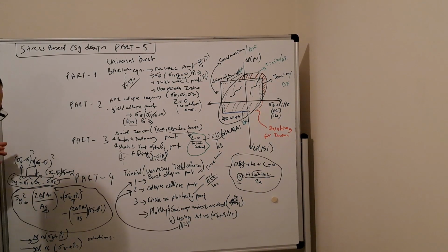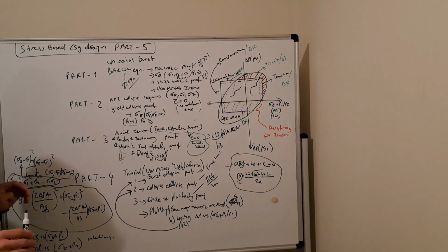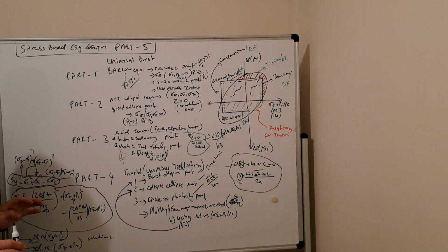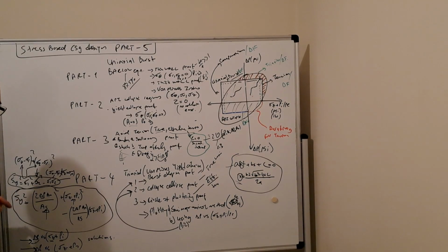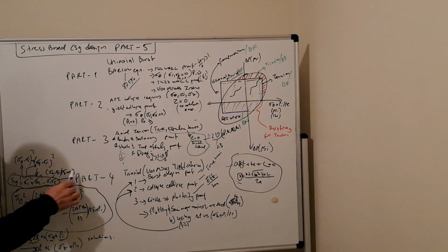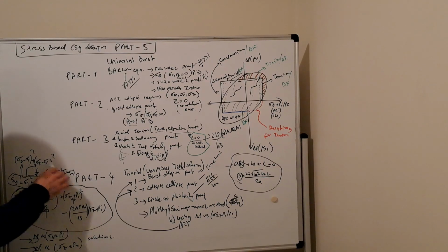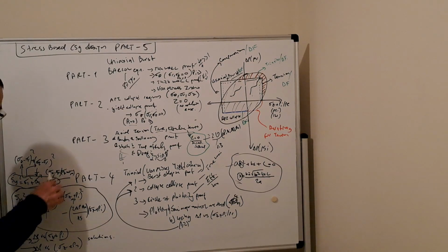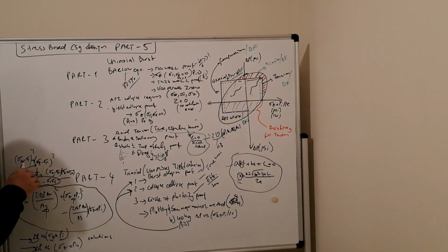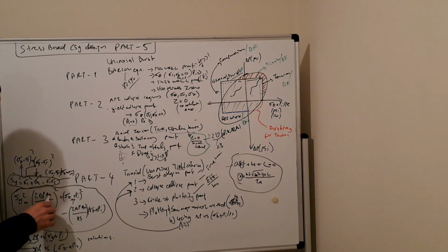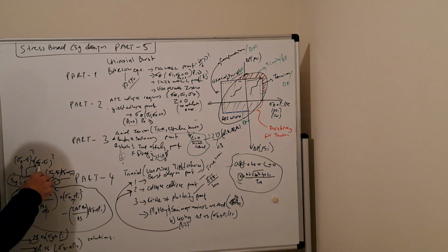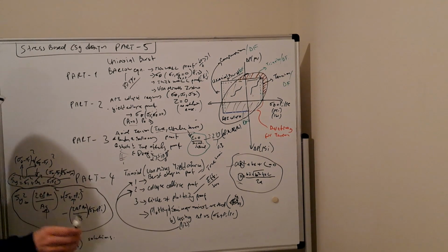The second method was to show the proof of each ellipse, and to come up with the exact solution for the delta P, or the differential pressure, or the difference between internal and external pressure. How did we do that? We came up with this simplification of the principal stresses, and then we take the difference between the tangential and radial stress, which is simply 2 times the delta P times the outer area divided by the cross-sectional area.